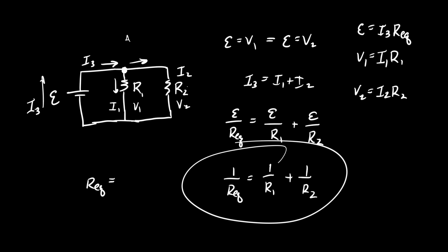Capacitors in parallel, you just add the capacitance. Resistors in parallel, you have to deal with the inverses. You guys see it? It plays by a different set of rules, especially since resistance is inversely related to the current, where capacitance isn't. There's no current passing through a capacitor. It's based on charge.